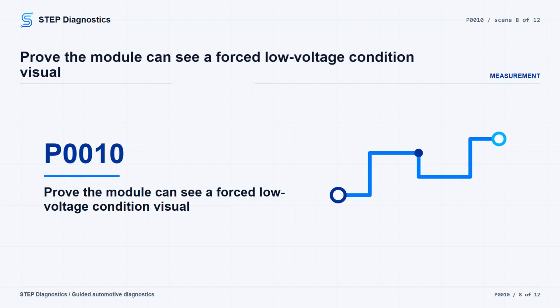You want less than 2 ohms between control circuit terminal 2B at the component harness and the other end of the circuit at the control module harness. If it is 2 ohms or greater, repair the open or high resistance. If it is less than 2 ohms, the path points to replacing the engine control module.